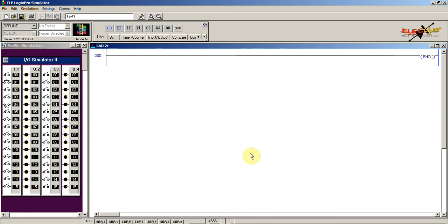Okay, here in this example we are going to illustrate the use of an off delay timer instruction, which is used to switch the motors off sequentially at 5-second intervals. In this case we will use three timers, and we will set the three timers to time delays of 5 seconds, 10 seconds and 15 seconds, and then we will close the input switch, and at that time